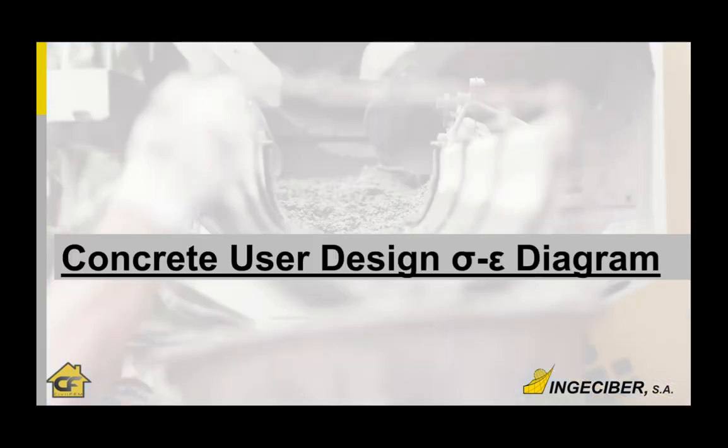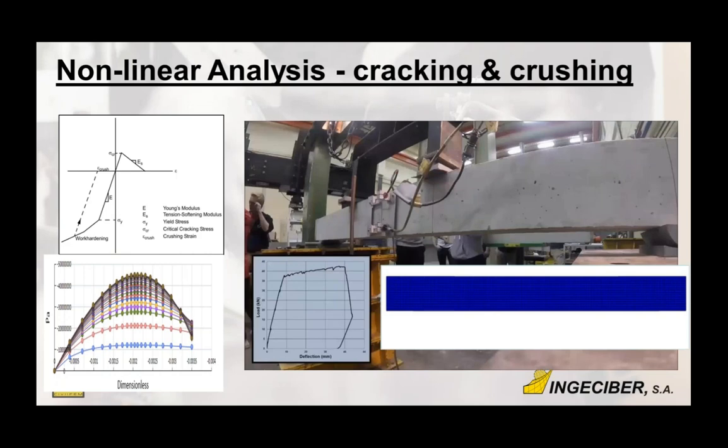Well, we are going to start with the concrete user design sigma-epsilon diagram. Just before seeing that, I will do an update of what CivilFEM already has for the concrete. In the concrete, we have the diagram for analysis and also for design. For the analysis, they are at the solution level, and they are for nonlinear analysis.